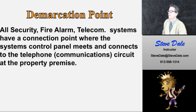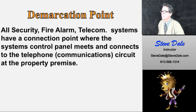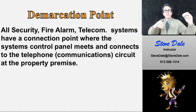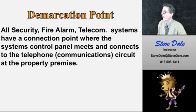And now let's just briefly talk about demarcation points. What is a demarcation point? Well, this is where the service provider, like a phone company, comes in and terminates at the premise. Okay, it's called a demarcation point. It could be like an RJ31X jack or some kind of interface that allows disconnection of the system by the phone company or the service provider, so they can work on their tester circuits. Okay, it's an FCC regulation.